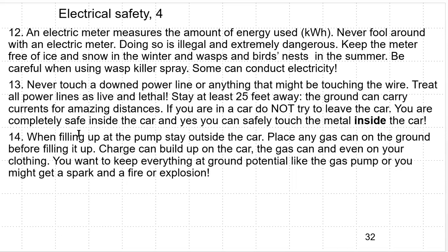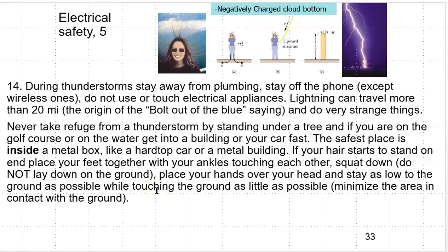When filling up at the pump, stay outside the car. Place any gas can on the ground before filling it up. Charge can build up on the car, the gas can, and even on your clothing and on you. You want to keep everything at the ground potential, like the gas pump, so you do not get a spark or fire and explosion.